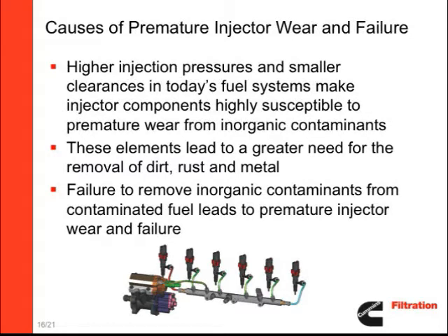With this understanding of the importance of using only the cleanest possible fuel in FIE systems, let's look again at the causes of premature injector wear and failure. Today's fuel systems operate at a much higher pressure than older systems. Higher injection pressures and smaller clearances make today's injector components highly susceptible to premature wear from inorganic contaminants. It is vital that rust, dirt, and metal particulates be removed from the fuel before it enters these precision systems. Failure to properly filter the fuel of inorganic contaminants leads to premature injector wear and failure.